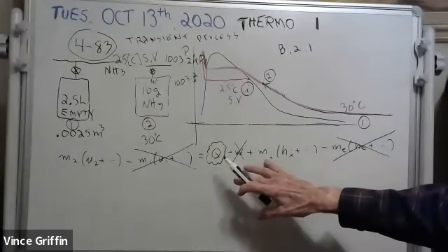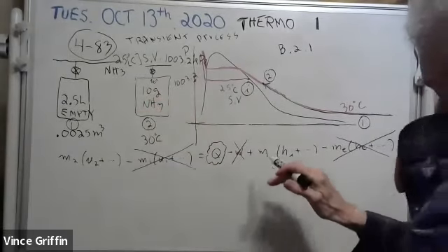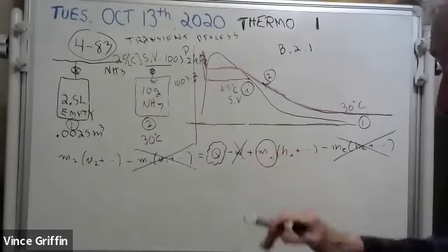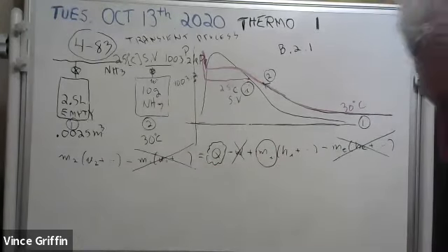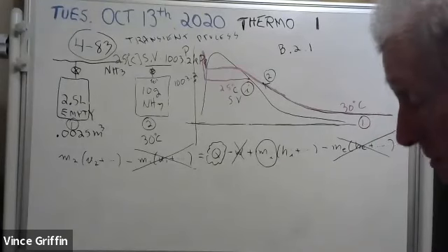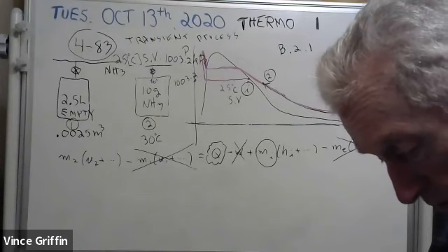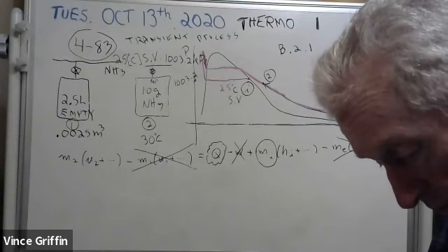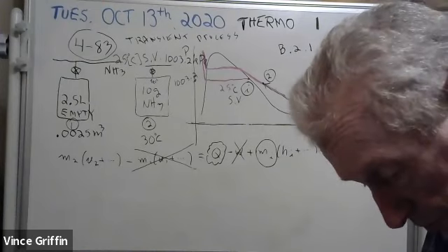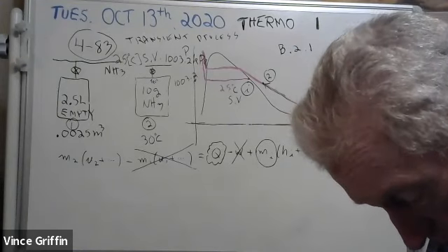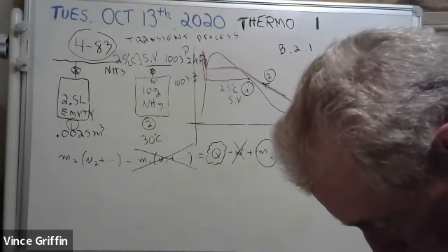Now, we know what this incoming mass is. They said it's 10 grams, so I'm going to circle it. And we could look this up. Go with me to the ammonia, and help me find the ammonia vapor dome. What we want is 25 Celsius. There it is: ammonia, 25 Celsius, saturated vapor.